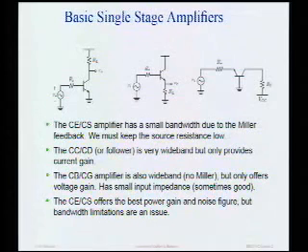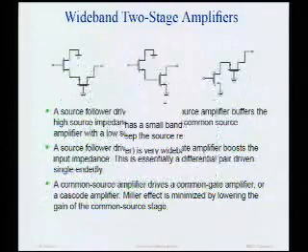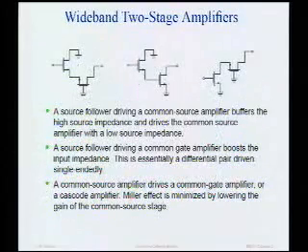As we'll also learn later in this course, the common source amplifier is actually probably the best amplifier, not only in terms of power gain, but also in terms of noise performance. So if we're trying to design an amplifier that has a very low noise figure, this is the topology of choice. So all we need to do is somehow fix this and make it more robust. Now, one way to fix these amplifiers is simply to go to 2 stages.